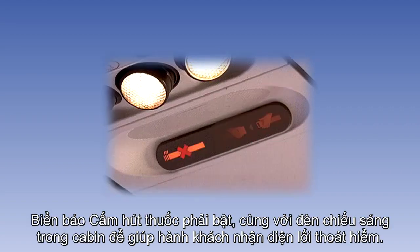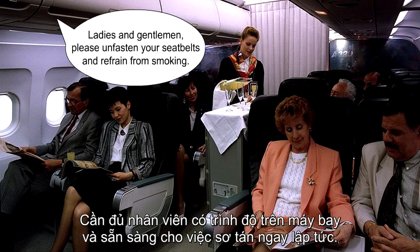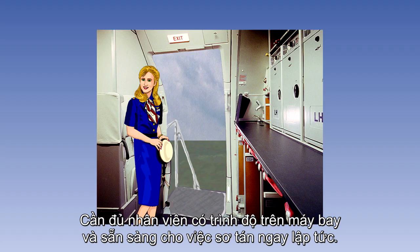The no smoking signs must be on together with the interior lighting to enable emergency exits to be identified. Passengers must be instructed to unfasten their seatbelts and refrain from smoking. Sufficient qualified personnel must be on board and be prepared for an immediate evacuation.